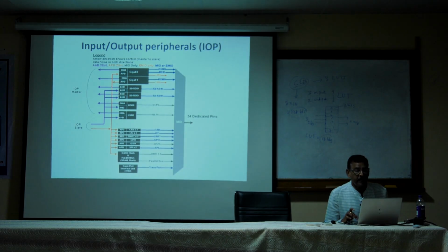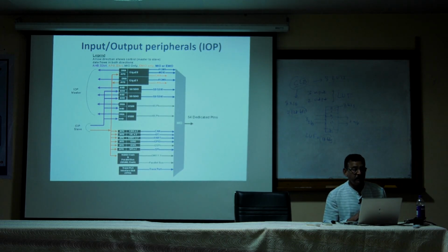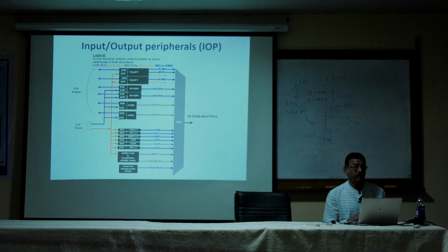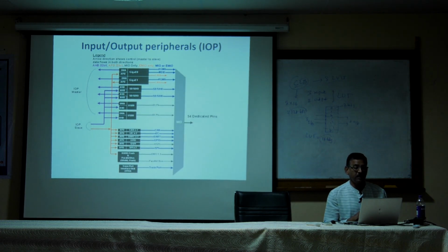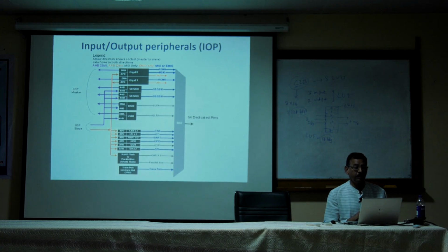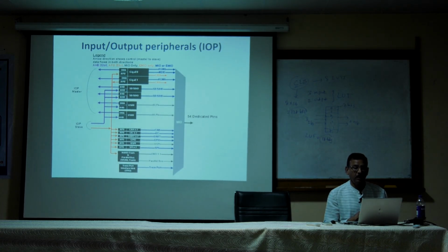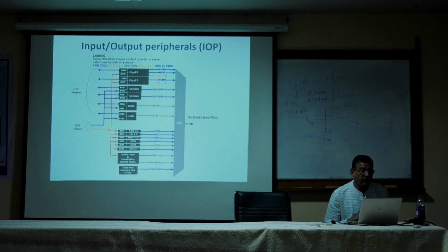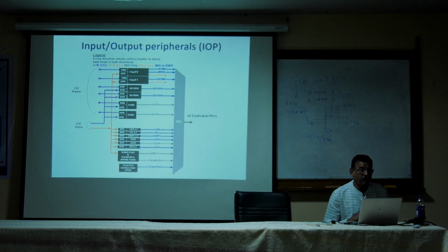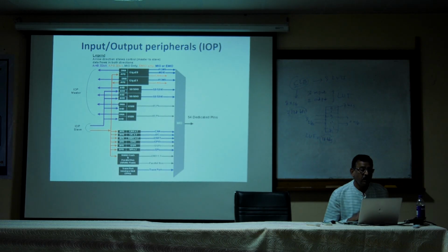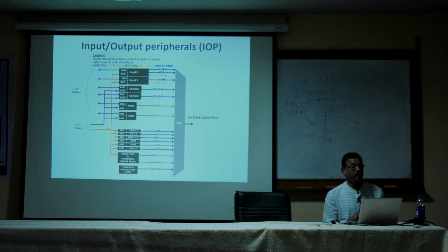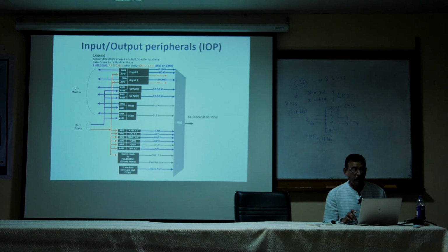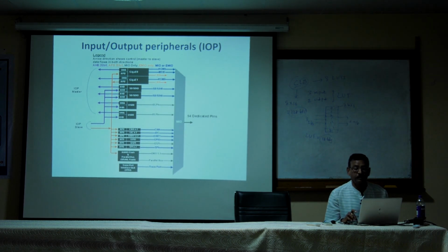There are 54 dedicated pins, MIO, as far as external is concerned, but these pins are shared across multiple functions. They can be shared for DMA or USB or maybe an SD card, so different functionality is there. These pins are shared across multiple operations, multiple functions.